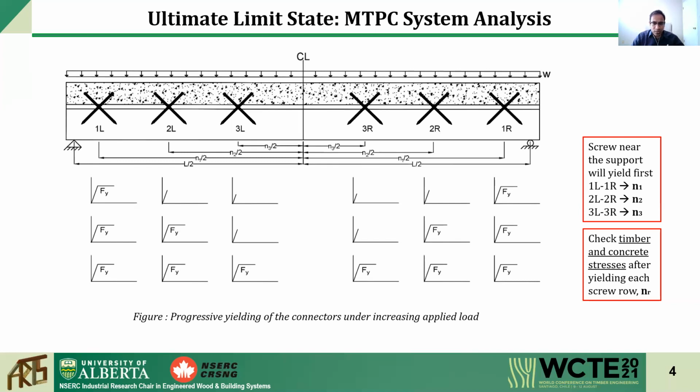This load redistribution process is called the progressive yielding mechanism, which leads to an elastic-plastic analysis for the entire system. We need to check the stresses of timber, either in tension or shear, and concrete after yielding of each connector.